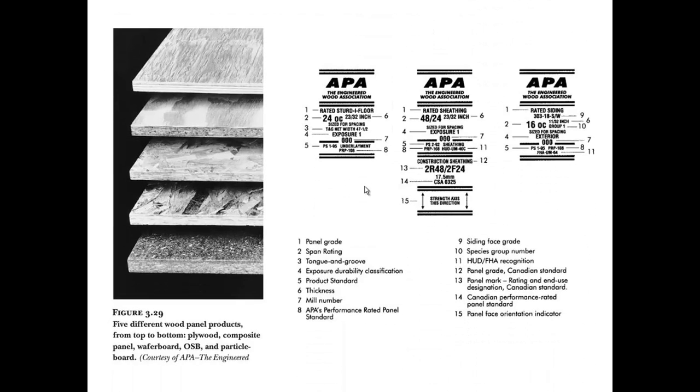So we use a lot of manufactured plywoods. Of course I always call this one regular plywood. We've got plywood, which is laminated veneers running in opposite directions for the grain every other layer. They're generally odd numbered layers, and they have a lot of strength in all directions because of that turning of the grains.